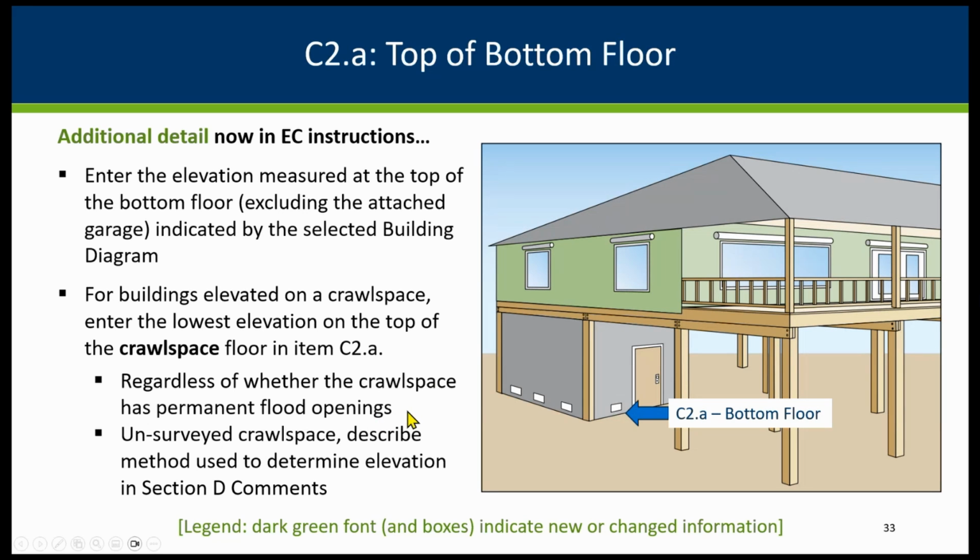Whether it's got the compliant flood openings will make a difference for whether it's compliant and meeting the local ordinance, and it will make a difference in the rating. But the surveyor filling out this section of the elevation certificate, they're not making the determination whether those flood openings are compliant or not. And so there may or may not actually be any flood openings there.